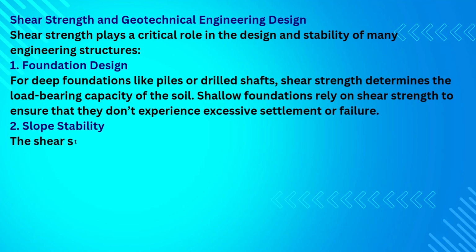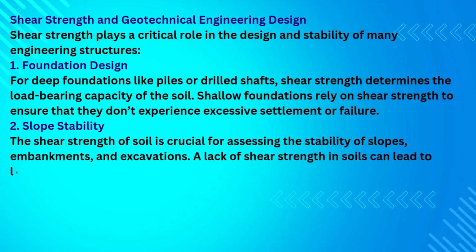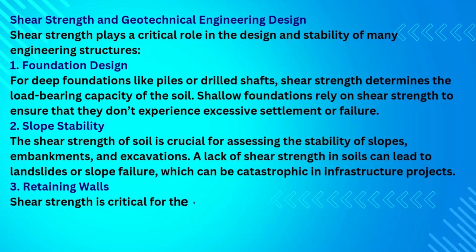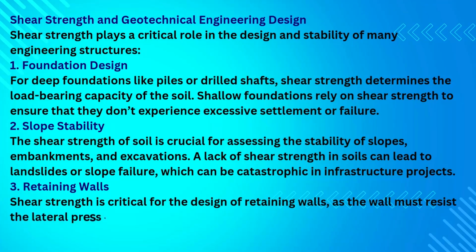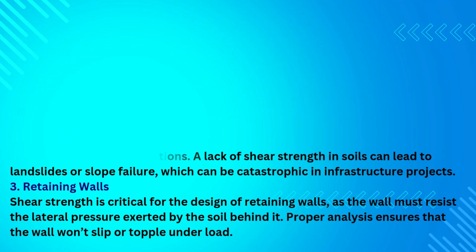2. Slope stability. The shear strength of soil is crucial for assessing the stability of slopes, embankments, and excavations. A lack of shear strength in soils can lead to landslides or slope failure, which can be catastrophic in infrastructure projects. 3. Retaining walls. Shear strength is critical for the design of retaining walls, as the wall must resist the lateral pressure exerted by the soil behind it. Proper analysis ensures that the wall won't slip or topple under load.